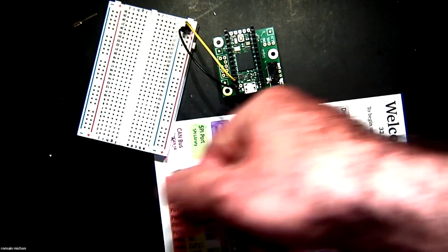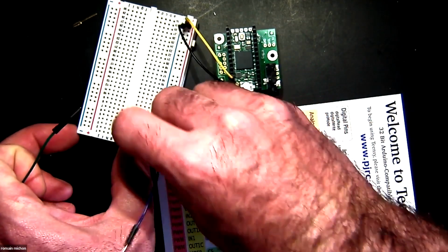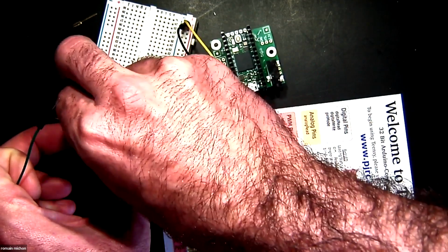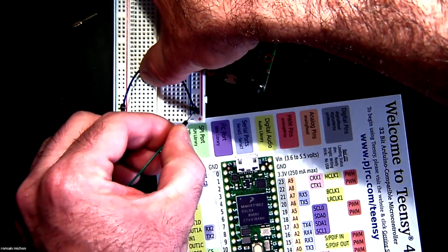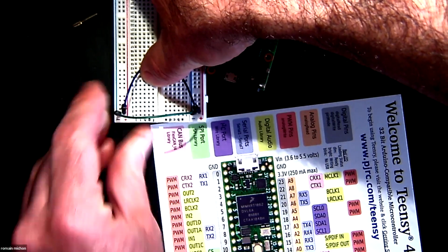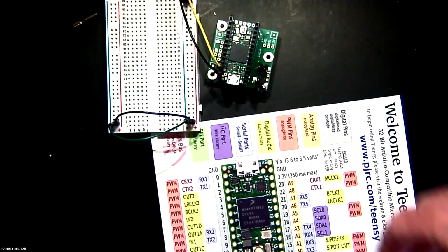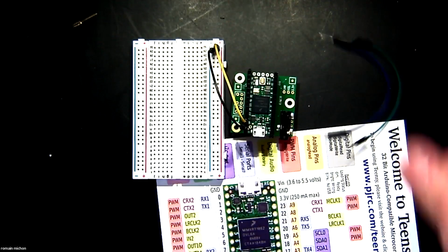So if you want to have power on both sides of your breadboard, you actually have to take power here and bring it here, and then do the same thing for minus. So now there's power on both sides, which is naturally going to be very useful for what we do today. I just wanted to tell you about this. Okay, cool. So I'm actually going to remove those wires.